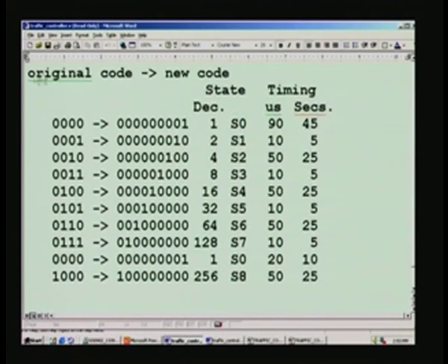See, what simplify does is, I mean, it is an optimizing tool. So, it normally allocates one-hot assignments for FSM states, and that is why it has this is state that we had requested, but the synthesis tool has made a one-hot assignment here, and this 0 state corresponds to 1, and this 1 in decimal I have put it here, and all these things are put by us here, and I need to just explain this out.